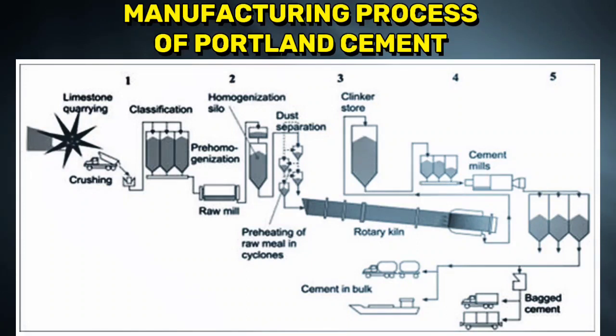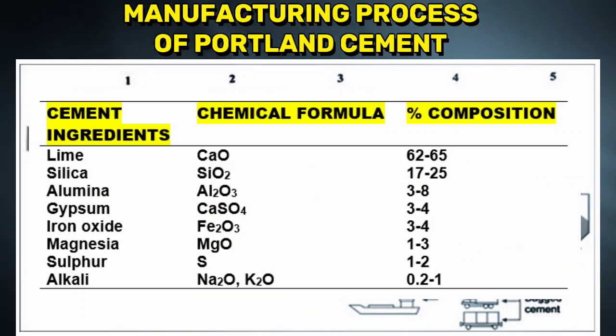So let's look at this flow chart for the manufacture of Portland cement. I just gave a little introduction about that. You can see step 1 here. What is happening here is the quarrying of limestone, a cement rock such as clay or shale. They are quarried, broken down and brought to the cement works. These rocks contain lime, calcium carbonate, and silica, which is sand, silicon dioxide. They contain alumina and some ferrous oxide. These are the raw materials for the cement manufacture.